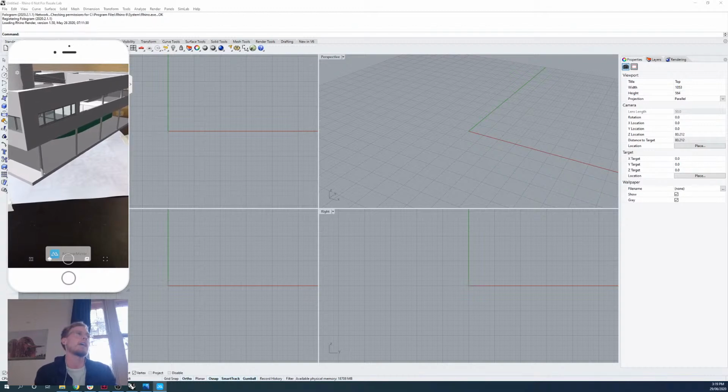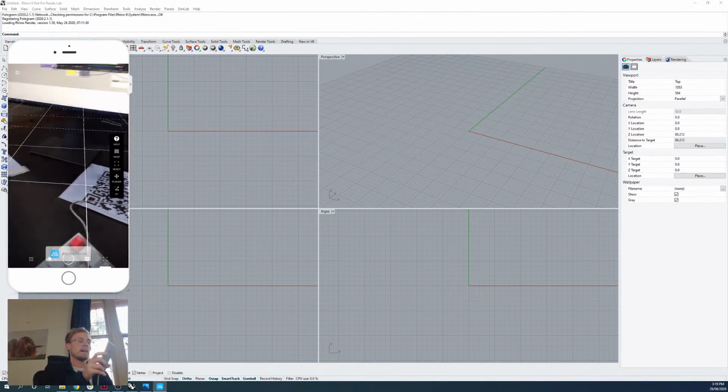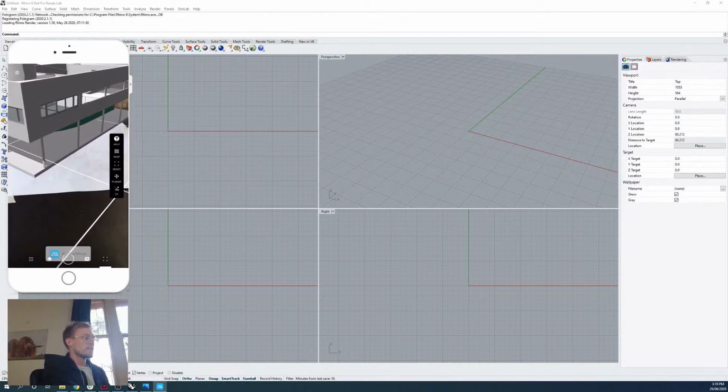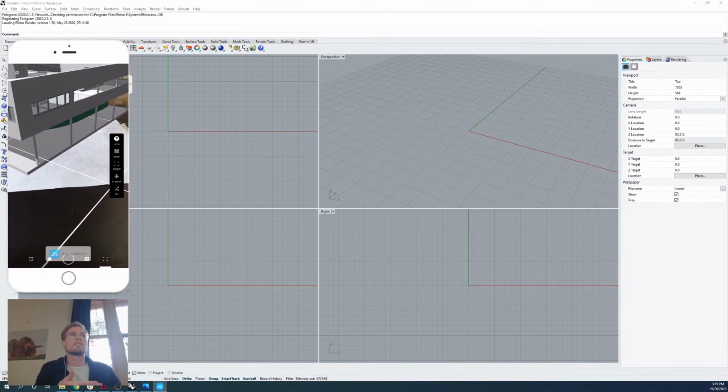The first thing we're going to talk about is the edit menu, and the edit menu is the square at the bottom right, which is just the four corners of a square. I'm going to click on it, and that'll bring up the edit menu. One hint I want to put out there straight away is whenever you see this square grid that fades off into the distance, that means you've got the edit menu open. It's important to note, because sometimes it's easy to try and do something in Fologram, like interact with an application, and you end up editing the location of your entire model because you've got the edit menu open. Obviously the edit menu interface is appearing, but also you have this fading grid that appears at the bottom of your model as well. So just be aware when you've got the edit menu open.